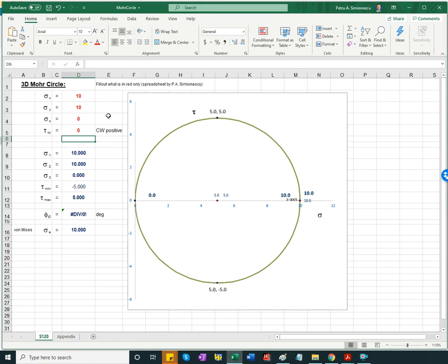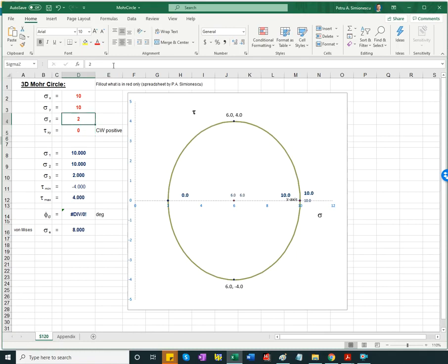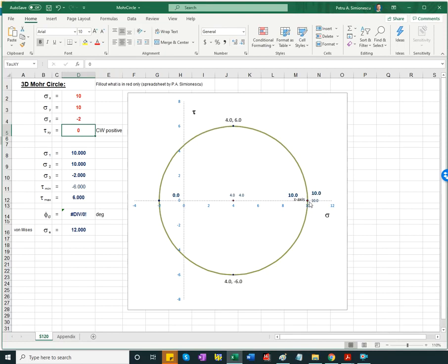If you do this analysis, say for thick wall pressure vessels, you may have here, let's say, the two, I don't know, I'm just making it up, and by the way, it has to be negative, it's inside pressure. And so again, the 2D circle is just one point with the negative pressure or normal stress due to the inside pressure. This is where the circle is shifted, and I can tell the maximum shear stress would be, in this case, 6.